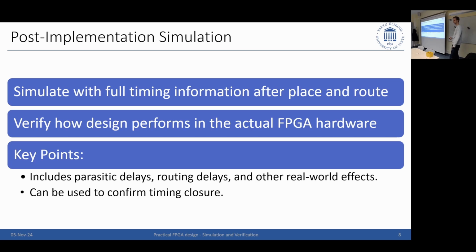And then, of course, with a hardware test you would not end up with a verified scenario. You just end up with your specific chip working with your design. So if you want to do a rollout of your design onto a lot of chips, or for space grade, where you have very high standards of verification, you want to do this kind of simulation because you can make sure that it will work on any chip which you will get. Because basically this considers the worst case chip manufacturing.